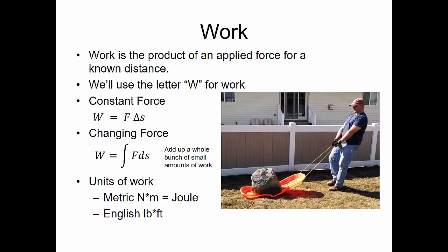We've defined work, that work is a product of an applied force for a known distance, or work equals force times a change in position, or if we have a changing force, work is the integral of the force with respect to position. Now let's put everything together, including our non-conservative work.